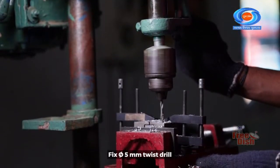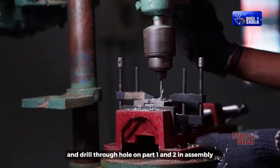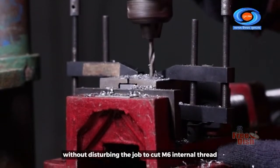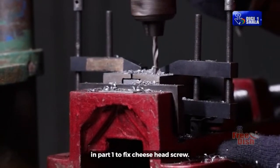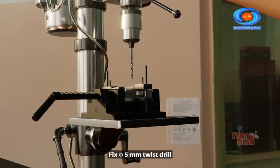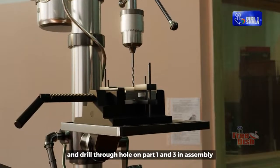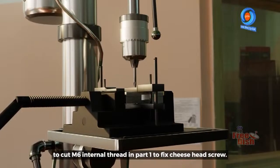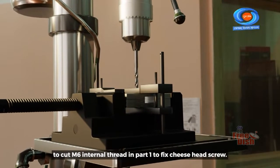Fix diameter 5 mm twist drill and drill through hole on part 1 and 2 in assembly without disturbing the job to cut M6 internal thread in part 1 to fix cheesehead screw. Fix diameter 5 mm twist drill and drill through hole on part 1 and 3 in assembly without disturbing the job to cut M6 internal thread in part 1 to fix cheesehead screw.